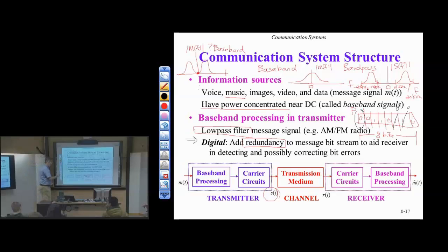All right, so that's the baseband processing in the transmitter. And in lab, we're going to do all of this baseband processing in discrete time, digital amplitude on the embedded processor, on the digital signal processor in lab. And homework, we'll do this primarily in discrete time and digital in MATLAB. And we'll use floating point in both cases. Okay, so right here I'm showing you continuous time analog from start to finish, but as we go a little bit farther into this material, we're going to do the work in the baseband domain, or for the baseband signal, in discrete time.